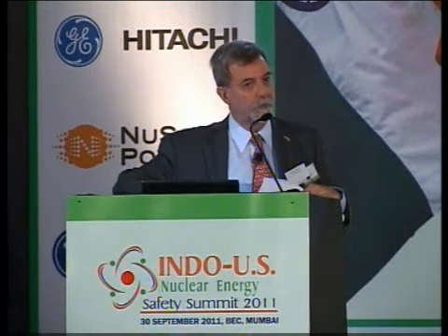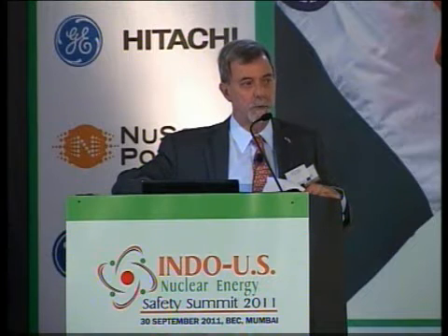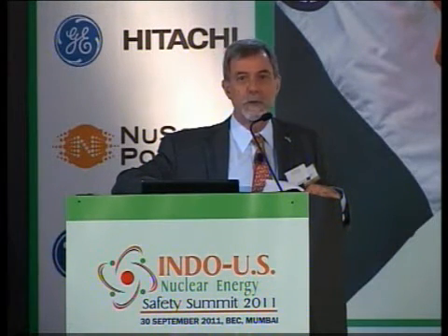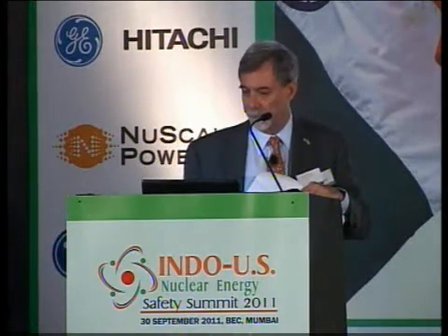The U.S. utility requirements: a number of years ago, the U.S. utilities got together and put together a requirements document of what they wanted to see in future plants. Their requirement was 1 times 10 to the minus 5th per year. And the AP1000 result is 5.1 times 10 to the minus 7th. So a significant improvement over current plants, current requirements, and even current U.S. utility requirements. Now, these levels of safety, as I mentioned before, can be achieved in other ways, and I'm not saying that only AP1000 can achieve those. We just achieve it in a passive manner as opposed to an active manner.